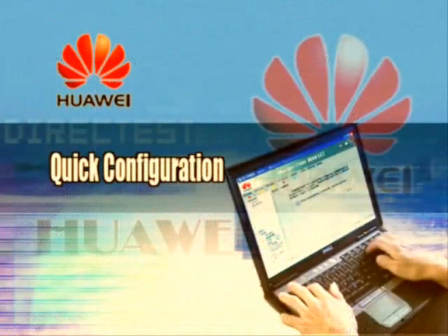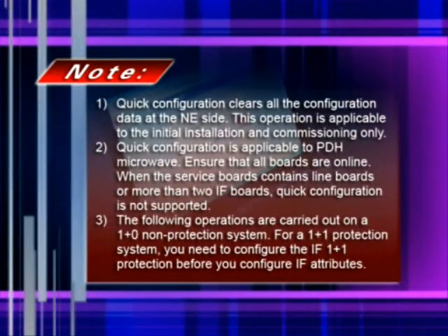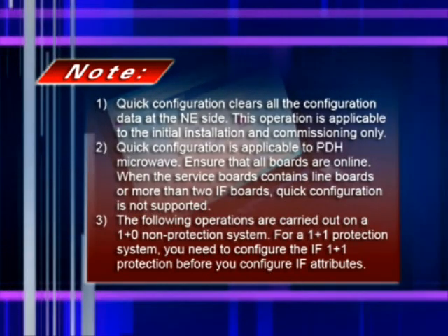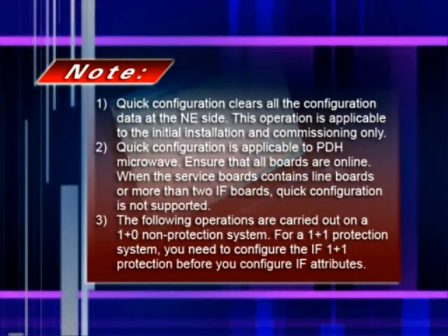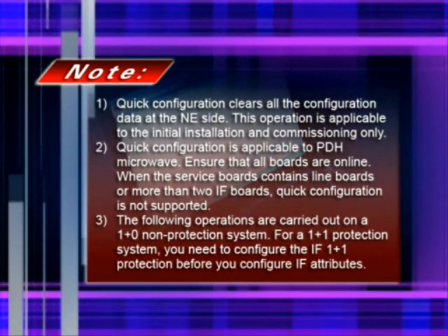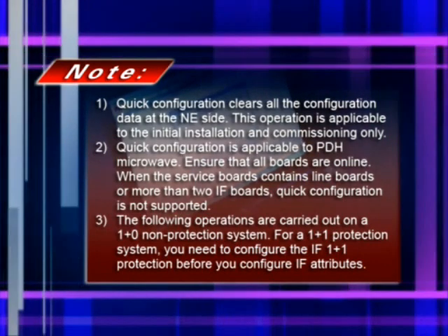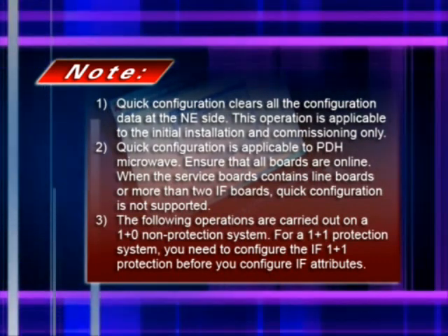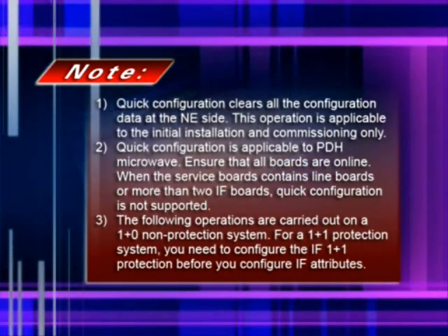3. Quick configuration. Note: 1. Quick configuration clears all the configuration data at the NE side. This operation is applicable to the initial installation and commissioning only. 2. Quick configuration is applicable to PDH microwave. Ensure that all boards are online. When the service board contains line boards or more than 2 IF boards, quick configuration is not supported.